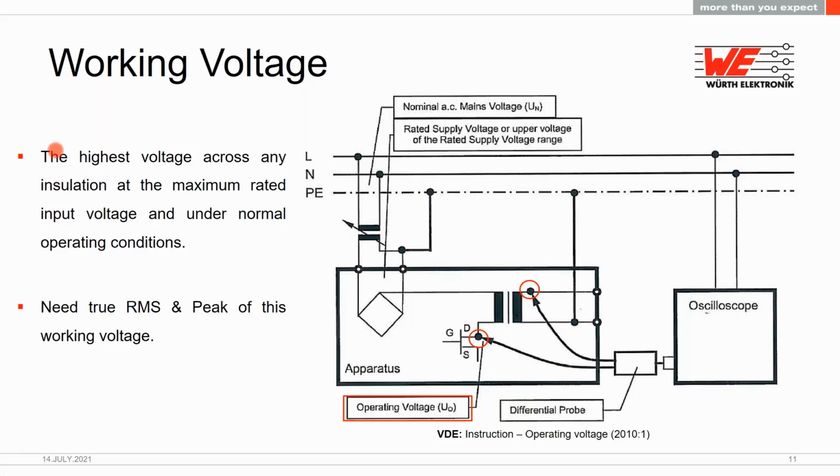Just like with the overvoltage categories and pollution degrees, as the working voltage increases, the separation distances required by the safety standards will also increase, which can lead to an increase in the size of the transformer. Likewise, the higher working voltage results in a higher dielectric test, which can lead to the need for additional tape and tubing that can add to the cost.